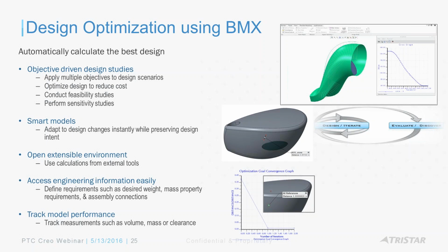As you know, in Creo, you can also create datums out of it, and you can also run some sensitivity and optimization studies. So you can have a goal telling that my center of gravity in my crankshaft, for example, should always be at the axis. I want Creo to help me in determining the counterweight. Traditionally, I know, during my industry days, I had to do a lot of trial and error. You go back, change the design, rerun the analysis feature and see where it is, things like that. So that's something that you can automate using Behavioral Modeler Extension.